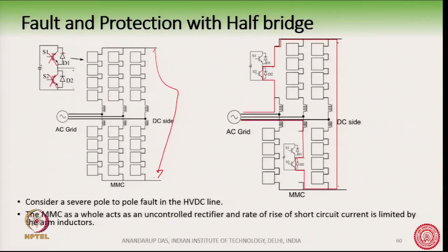So, how does the circuit look when the diodes are conducting? In order to understand this, I have drawn this circuit here. In this circuit, for this phase A, for example, we are representing the entire arm by a single half bridge. It is for the purpose of analysis; if we have more half bridges, the same analysis will be valid.